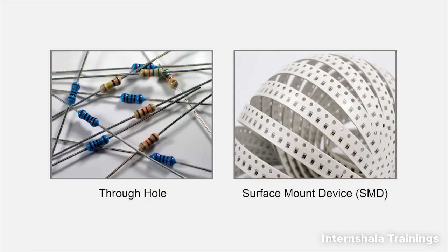From a price point of view, both of them have a similar price. But in the case of the through-hole resistor, as its size is big, it's obvious that it's going to take more space on the PCB. And if we consider space as an aspect, then through-hole resistors are actually more expensive, because they take more space on the PCB, which results in a larger PCB size and, as a result, an increase in price. So through-hole resistors indirectly increase the price of the product.